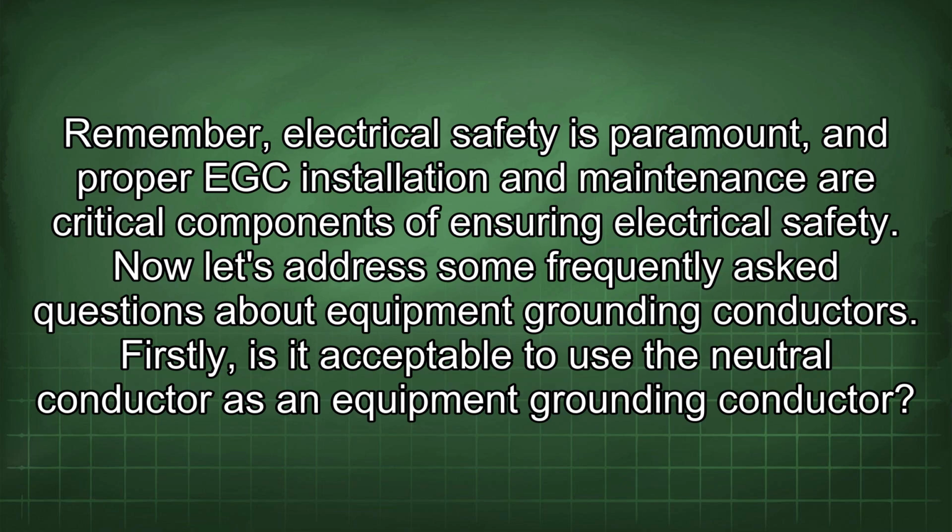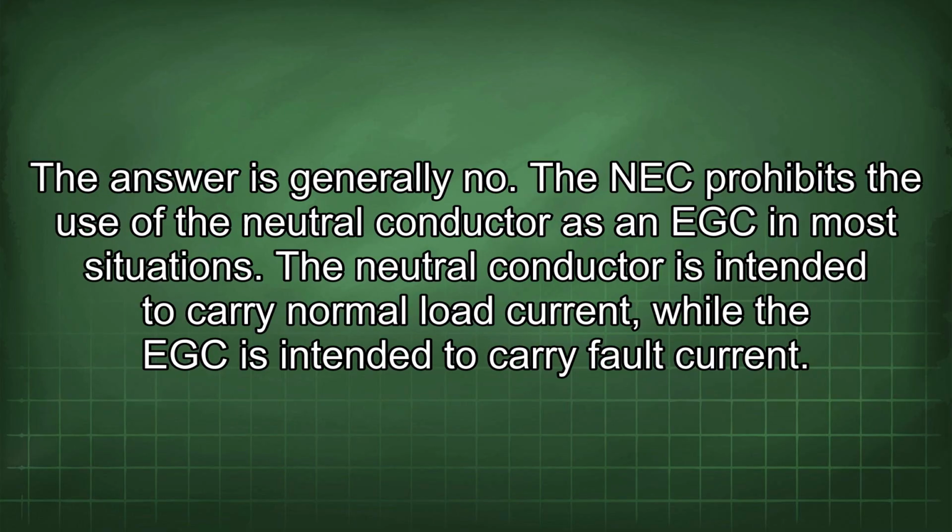Firstly, is it acceptable to use the neutral conductor as an equipment grounding conductor? The answer is generally no. The NEC prohibits the use of the neutral conductor as an EGC in most situations.